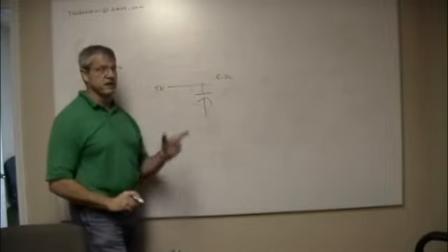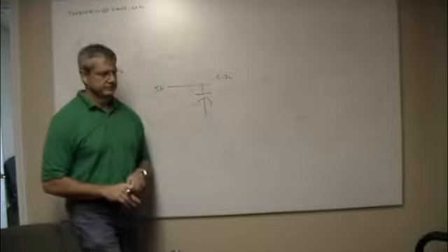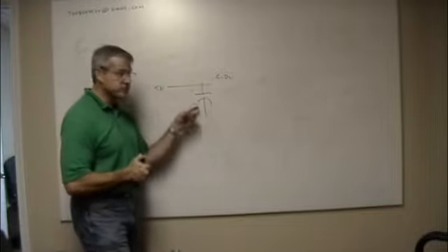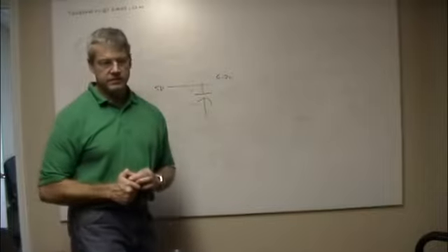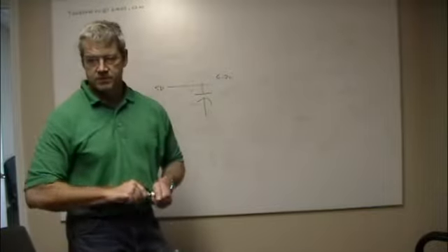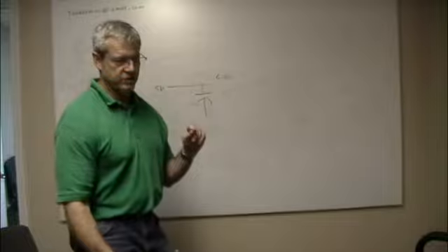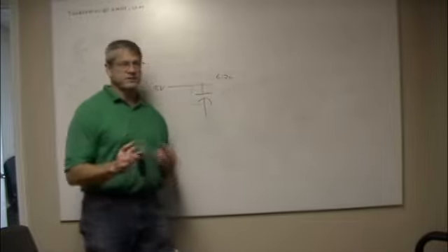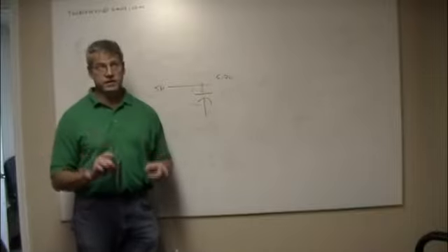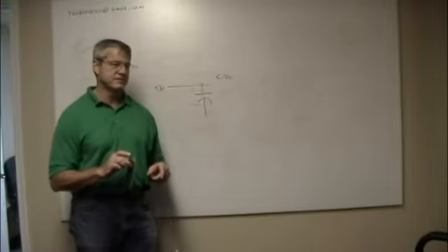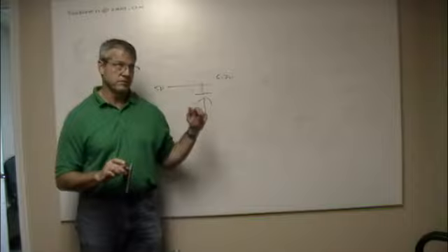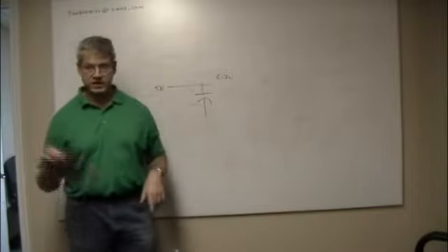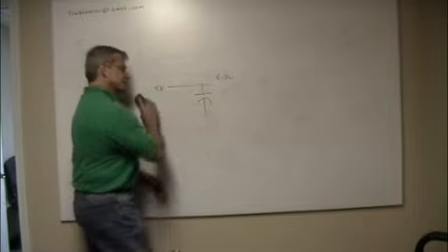What happens is as they get higher voltage, they just get bigger. The reason for that is most capacitors are in the plus or minus 20% range, and that has a direct effect on charge capacity. So if they're on the low side, they can overcharge, and that can cause them to go bang or heat up like that one did out there.